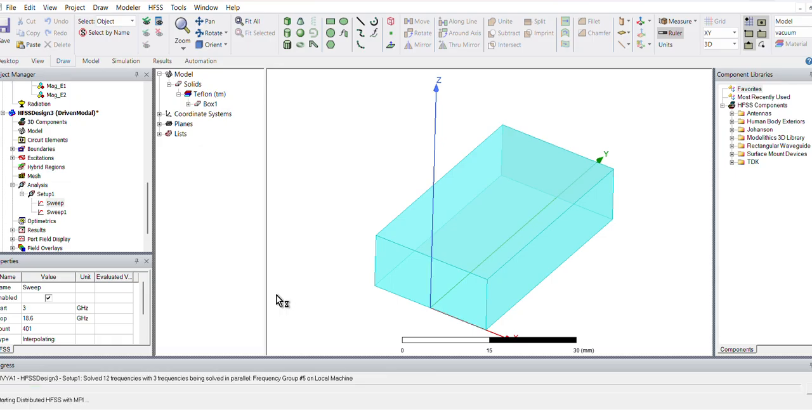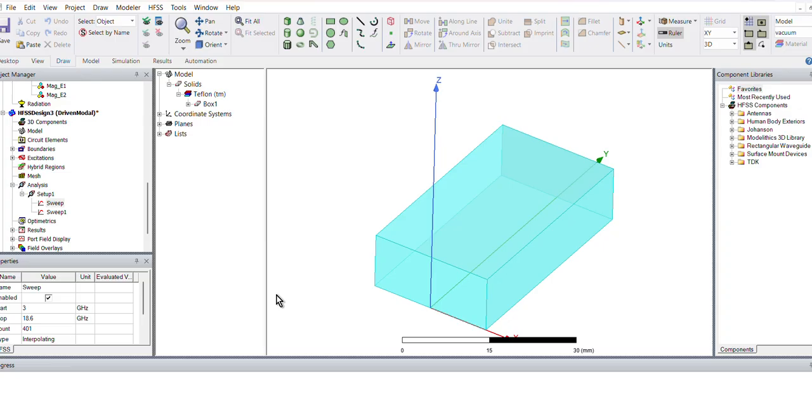Whenever we are simulating an SIW structure, we need not simulate an SIW structure. We need not put in the PTH and everything. We can design it as a dielectric filled waveguide, and later on we can replace the side PEC layers with PTHs. That way it will be SIW. What is the beauty of that? That simulation will take much less time. See, my simulation is already completed. So we shall go through the whole idea that I just told you.